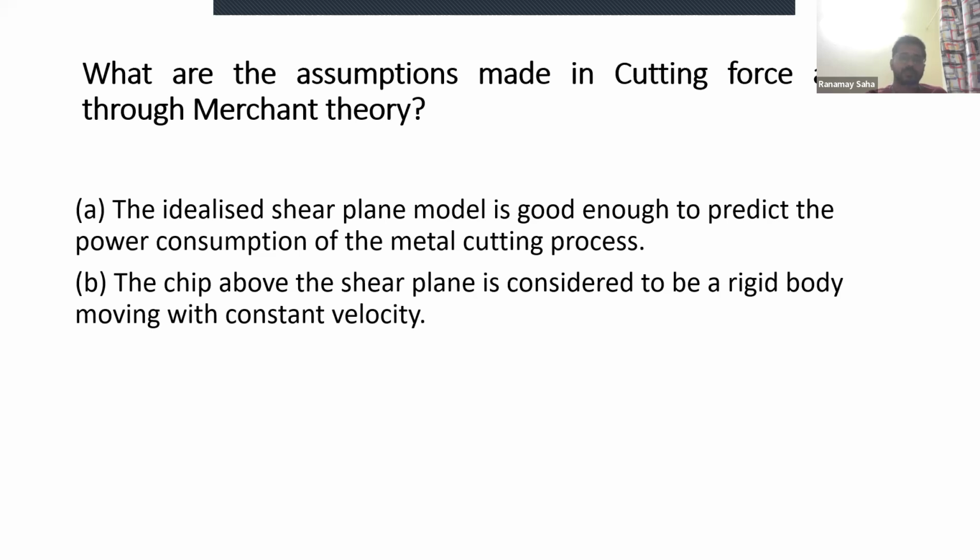You have to assume that the shear plane model gives you a good prediction of the power consumption. Otherwise, you have to consider some errors while analyzing the cutting forces. So it is assumed that this shear plane model is good enough to get you the power consumption data.